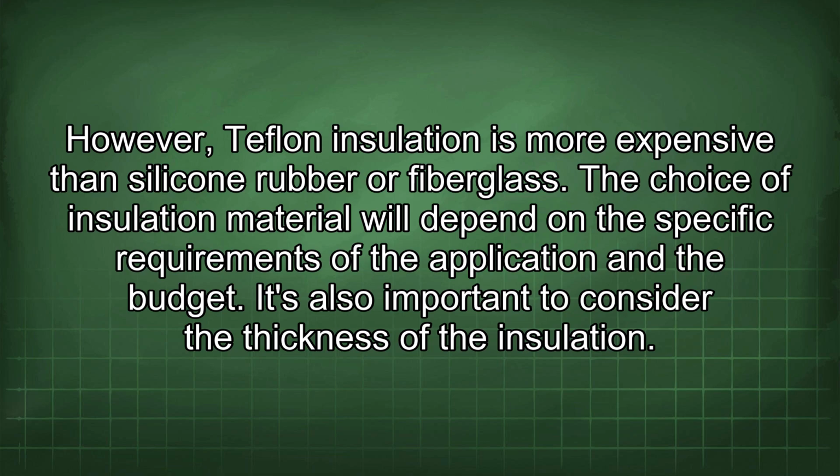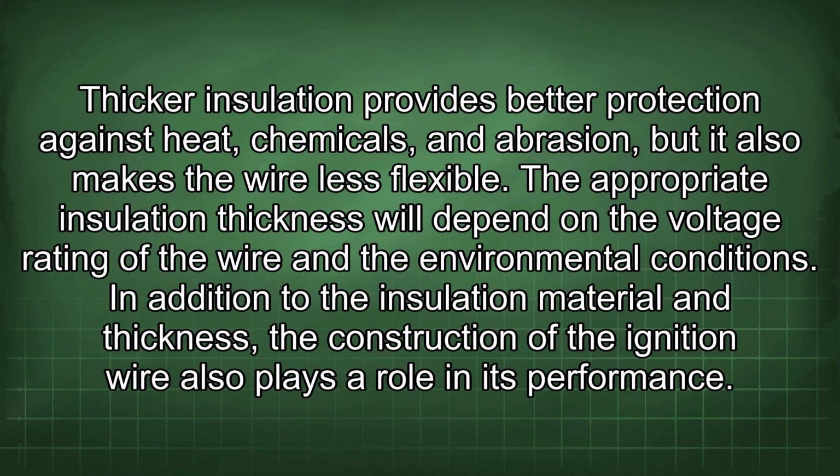It's also important to consider the thickness of the insulation. Thicker insulation provides better protection against heat, chemicals, and abrasion, but it also makes the wire less flexible. The appropriate insulation thickness will depend on the voltage rating of the wire and the environmental conditions.